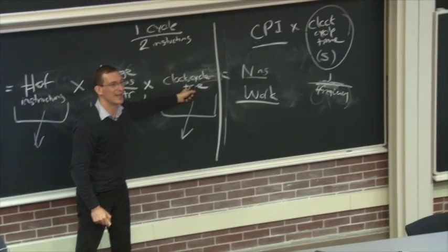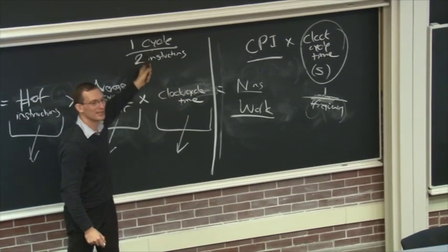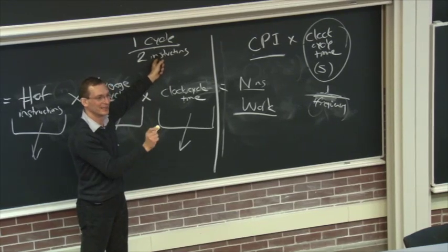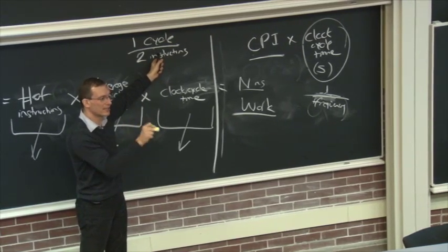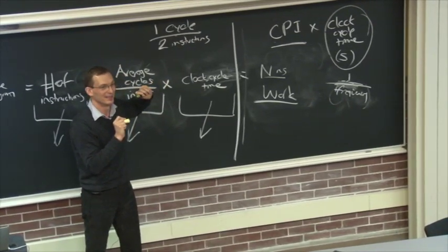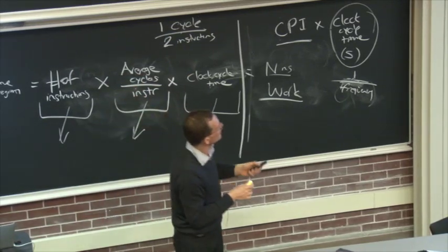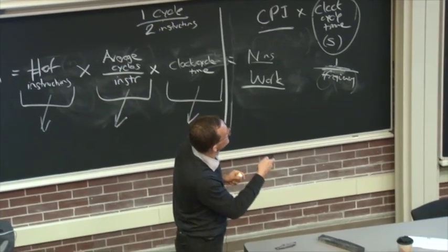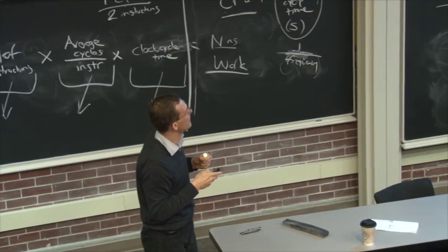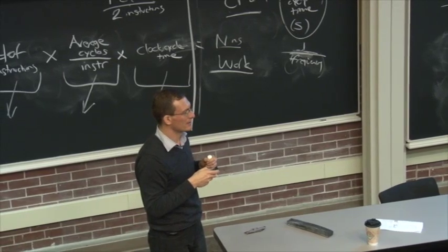Hopefully. If you provide additional hardware, obviously you need additional hardware to execute multiple instructions per cycle, right? You cannot reuse the same hardware if you're executing multiple instructions per cycle. So think about these trade-offs. But basically, we will see many methods to do this. The same cycle is devoted to processing multiple instructions. And actually, pipelining does that, right? We'll see this in more detail.